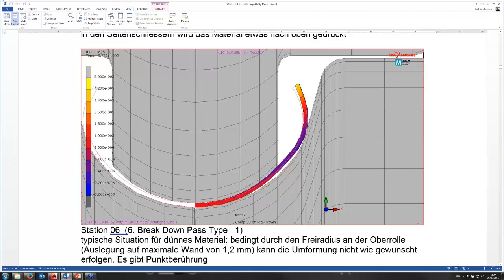And here in this particular breakdown we begin to see some essentially flat elements, whereby we haven't had sufficient forming force in this area to deform the strip. Again, this can be attributed to the clearance we have for the thicker gauges. So the problem we have now is overcoming this in the latter stages of the roll train, or maybe we change the top roll. This could be a valid reason for us to make an additional top roll for this material variant. In other words, to help us form this shape correctly.